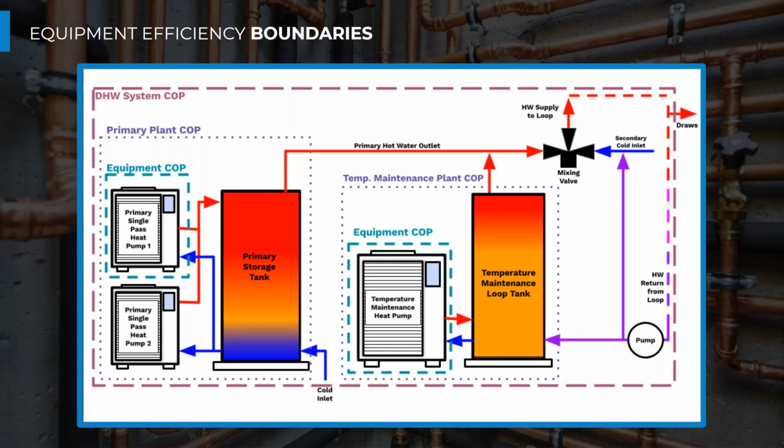Yeah, and I'm not sure I answered that person's question fully, but overall, if we locate these R134A heat pumps in the parking garage, we can run them during the winter or those cooler times of the year. And that's much more advantageous for our overall system COP than the slight difference in temperature we get because it's in a cooler space in the garage during some time. So in general, it's actually better to be able to provide heat to the system at all times of the year, even when it's cool outside.